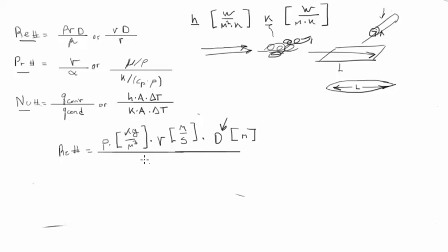This is divided by the viscosity, the dynamic viscosity, which is the stickiness of the fluid. This is in units of kilograms per meter second. Honey will have a very high dynamic viscosity, something like water will be lower, and air will be even less than that. If you look at the units here, you'll see they all cancel out. All three of these numbers are dimensionless. So this contributes to the viscous forces, the stickiness of the fluid.